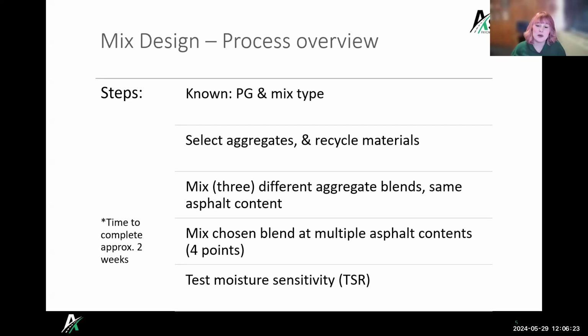So why should I want to see that mix design? The main reason is you want to make sure that the mix that's coming out to your job is going to meet the specifications. You have your design, so hopefully the design was done correctly and you've designed the right mix for your application. And now you want to see that the mix design, that recipe they're using back at the asphalt plant, is going to meet those specifications.